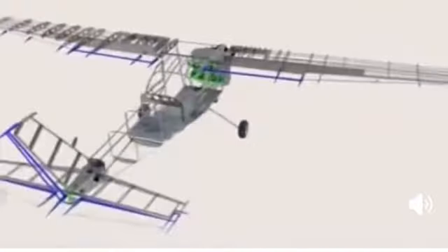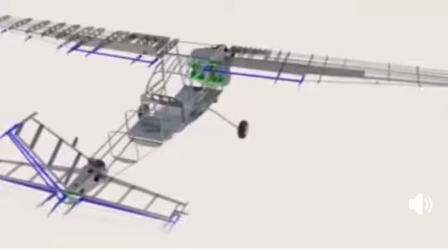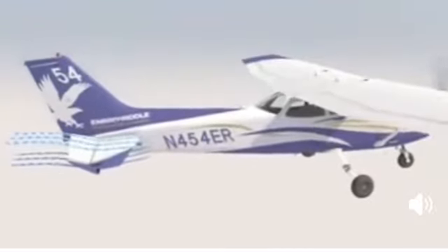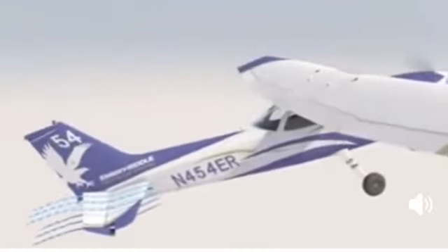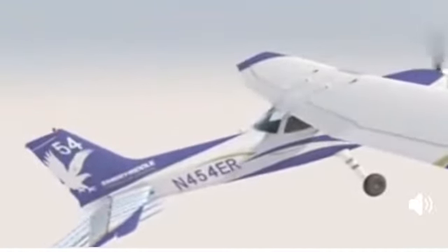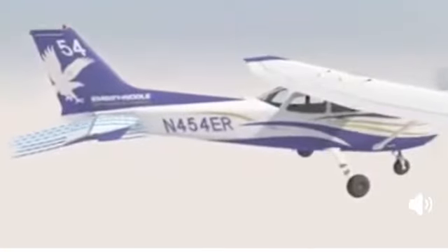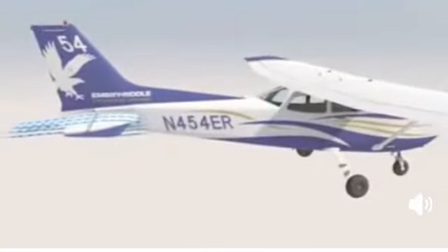In most general aviation airplanes, as the pilot moves the controls, he or she is moving steel cables or push rods connected through other linkages that physically move these controls. As the control surface is deflected, the airflow is changed, which results in an aerodynamic force changing the airplane's path through the air. Let's investigate the three primary flight controls in more detail.